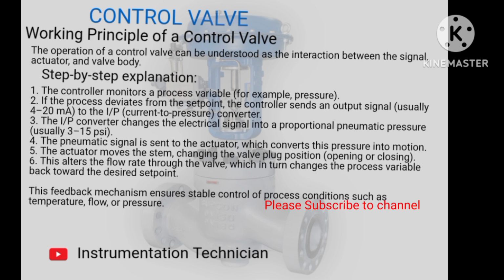The pneumatic signal is sent to the actuator, which converts this pressure into motion. The actuator moves the stem, changing the valve plug position, opening or closing. This alters the flow rate through the valve, which in turn changes the process variable back toward the desired set point. This feedback mechanism ensures stable control of process conditions such as temperature, flow, and pressure.